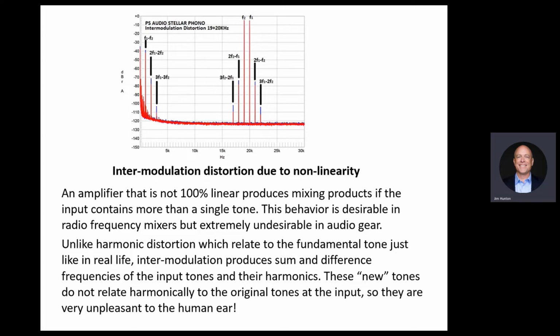How do you fix either one of those distortions? By making the circuit a lot more linear, or by fixing the distortion with some negative feedback. But a phono designer, because it's low levels, will try and up the bias as much as possible, try and get to an operating point where you have the least distortion, and then fix if you need to. Okay, sometimes you don't need to. Sometimes it's an acceptable level of distortion, and the fix for it has side effects that you can hear. Okay, and we'll maybe talk about it very quickly.